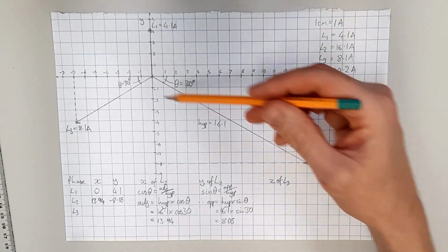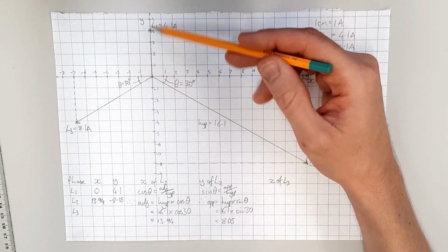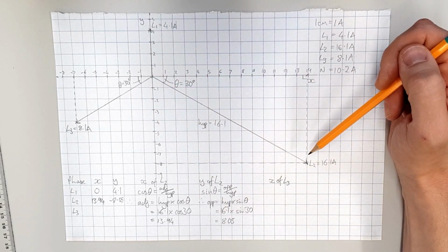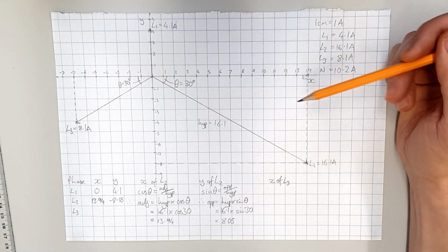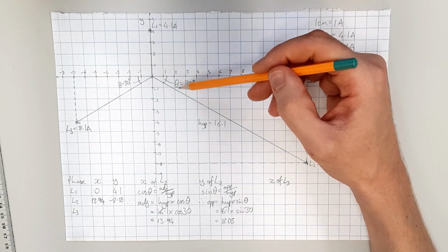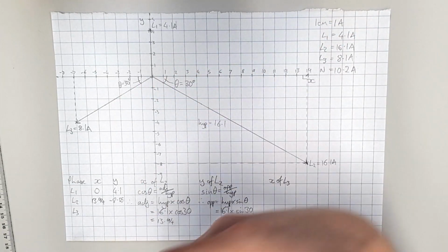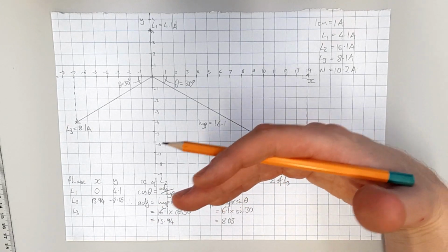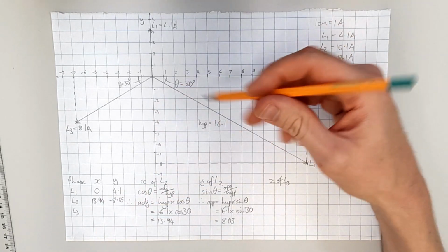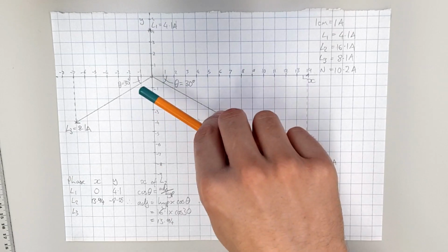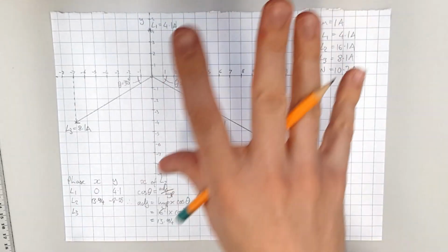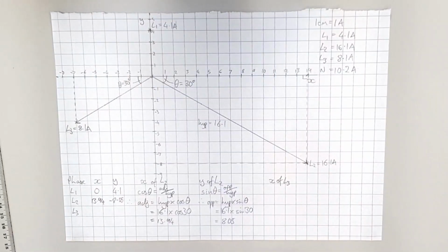It's worth noting at this point that this is a purely resistive load that we've got here. Because it was just heating loads, it's pretty much purely resistive, which means that the angles between the currents will be 120 degrees. Where you start incorporating motors and things like that, then it may be that these aren't quite at 120 degrees from each other, but that's the subject of a much future video.